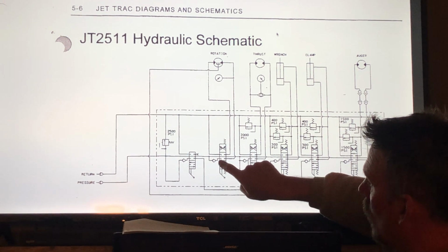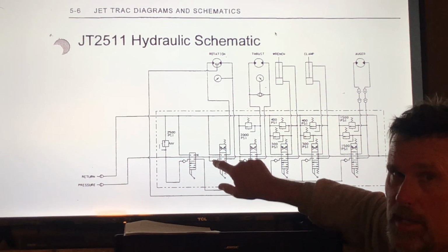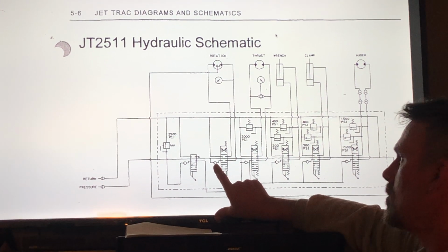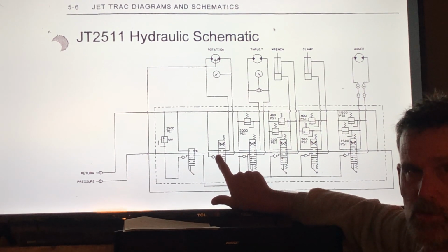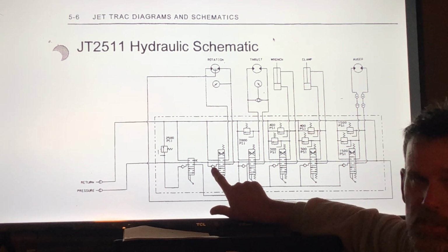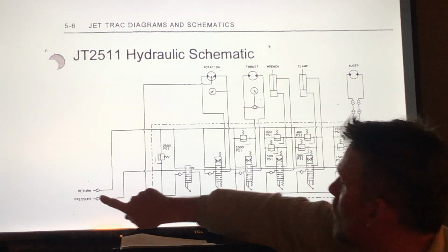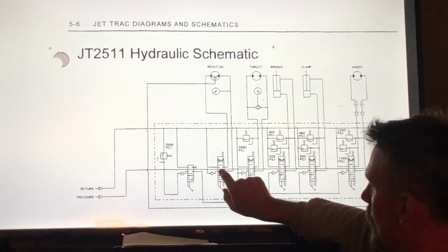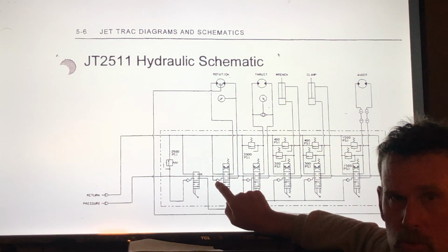So, when it connects, it's going to drop down somewhere around 1000 PSI and the bucket will drop. But by putting in this load check valve, okay, that 2000 PSI tries to go back in the line and it slams the check valve shut. So now the pressure line, because you moved the spool, it's blocked through the center. It has no choice but to come over against the load check.